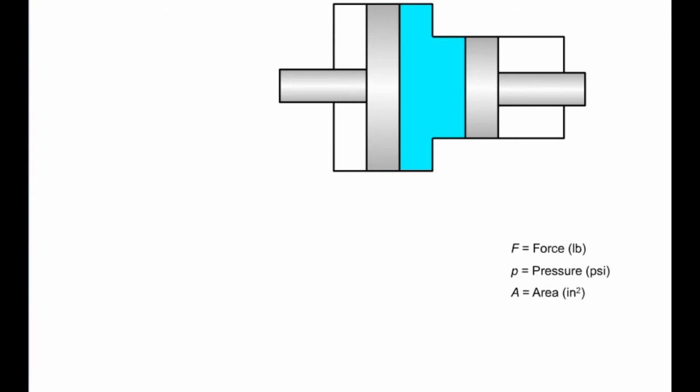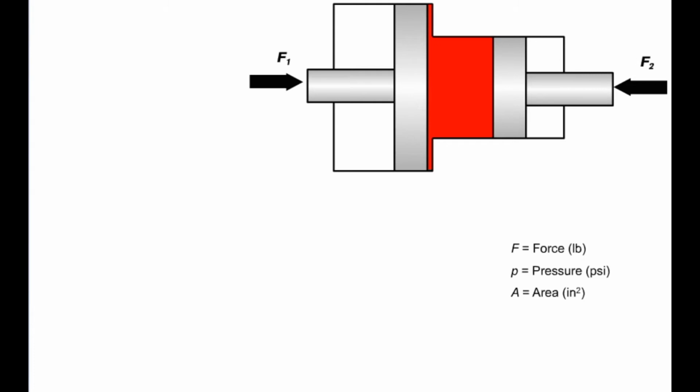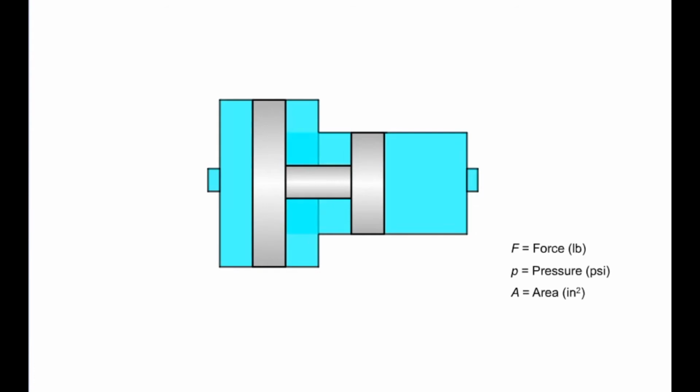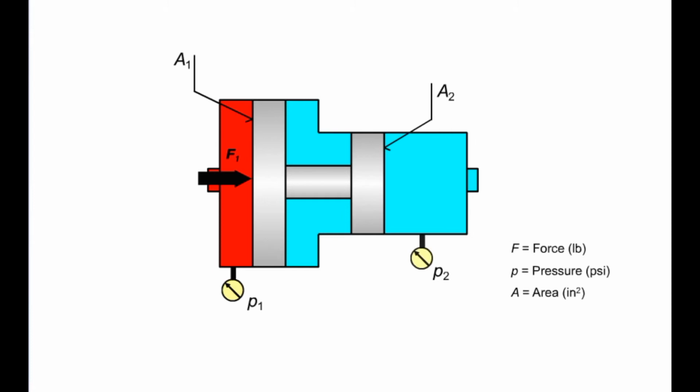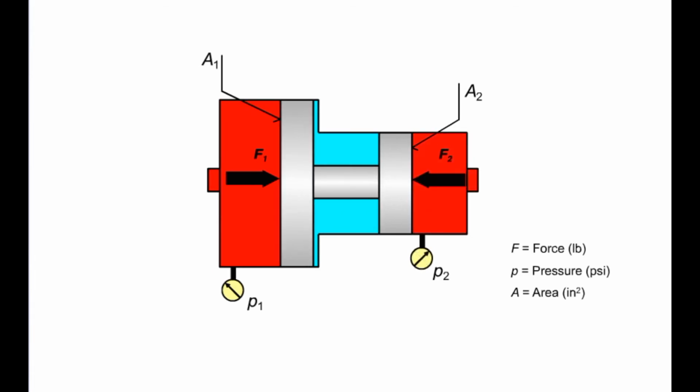We have previously been looking at how force is transmitted hydraulically between two pistons. The forces have been applied to the system or transmitted from it by mechanical elements such as the piston rods. We now look at the concept in another way. Two pistons of different sizes are connected by means of a rigid bar. Under the application of pressure P1 on surface area A1, force F1 appears. Force F1 is transmitted by the bar to the surface area of the smaller piston A2, giving rise to pressure P2. The forces F1 and F2 are in equilibrium.